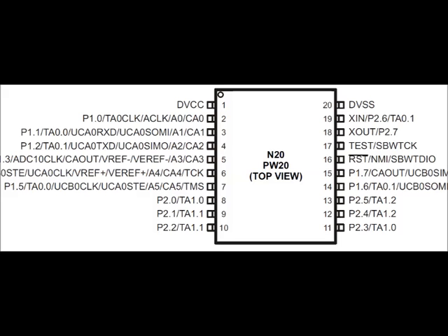Now the reason we're using TA0CCR1 for our comparison register is in the question we've been told that we want to toggle a pin on P1.2, and having a look here at P1.2, we note that it's connected also to TA0.1. Now, TA0.1 indicates timer 0, comparison register 1. Hence we want to be able to use our TA0CCR1 as our comparison register to actually toggle this particular bit.